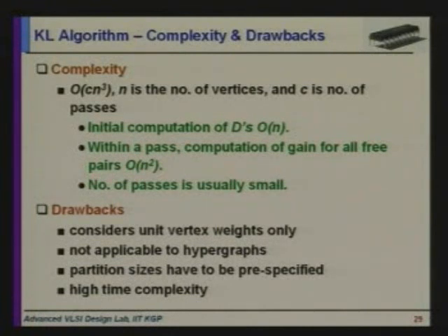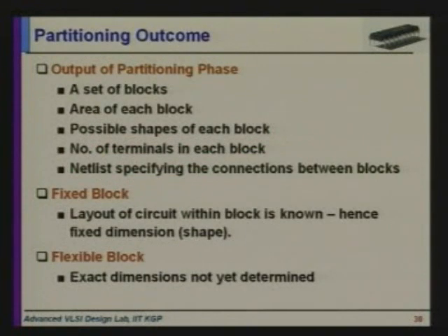Drawbacks of this algorithm: it considers unit vertex weights only, right? Not applicable to hypergraphs. That means it cannot be considered for big nets. Partition sizes have to be pre-specified, and there is high time complexity. So there are many other algorithms that have been developed.